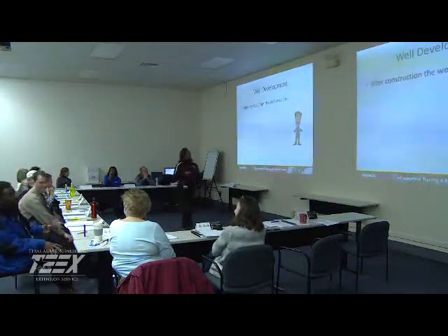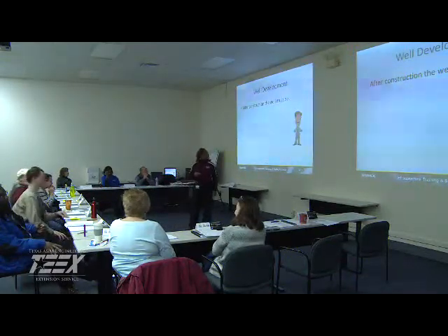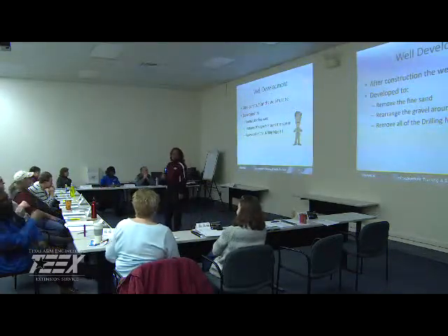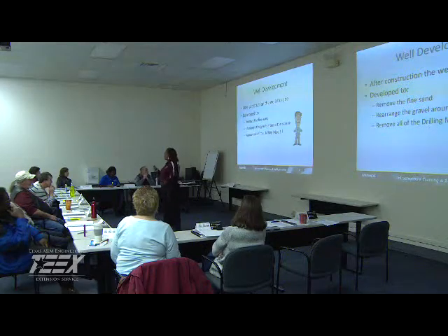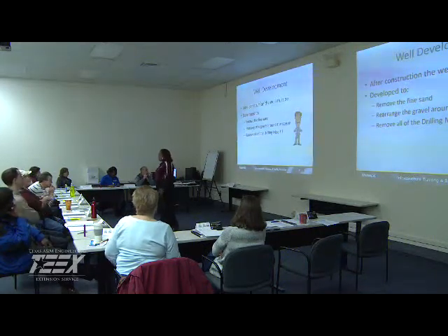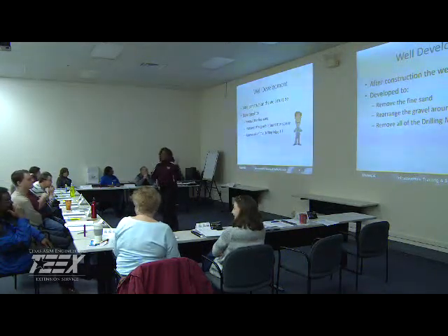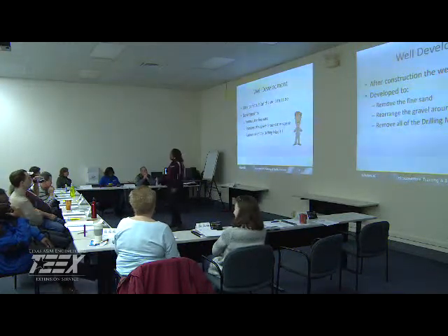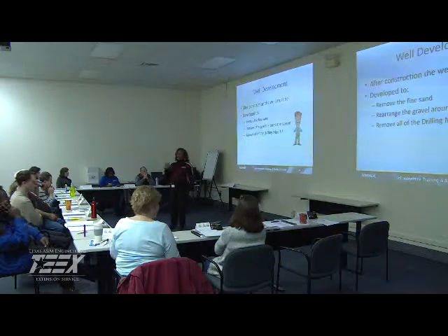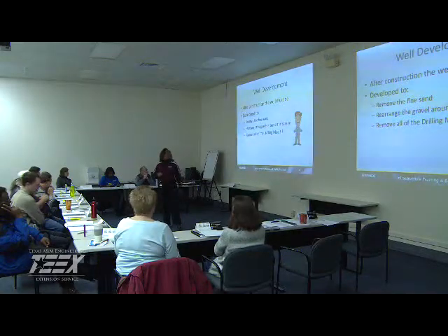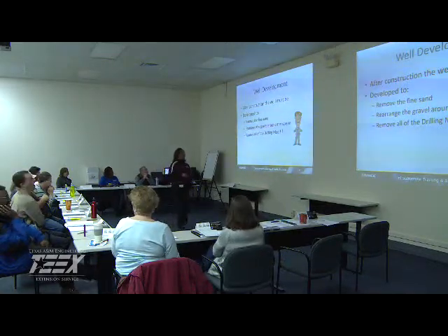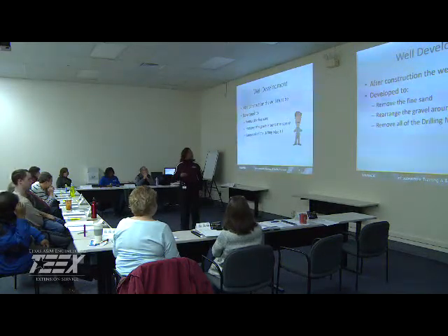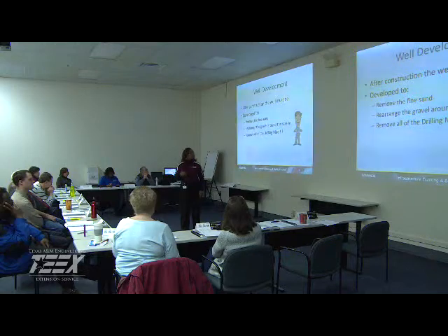All right. So after construction, the well must be developed. And what do we mean by developing a well? As we are drilling, all that stuff that we're putting down there, we want to make sure that we're taking it out. And of course, during the drilling process, you want to make sure you're using chlorinated water. But it's developed to remove the sand, to rearrange the gravel around the screen, and remove the drilling mud that's put in place.